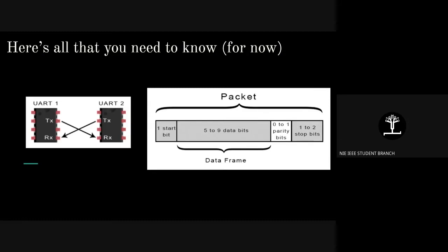First, whatever data is to be sent is initially on a bus, and from the bus, the 8-bit data with the start bit gets latched into something called a data register. We have a data register where all the 8 bits will be filled, and in parallel from the data register, it gets shifted onto the shift register. The shift register's job is to append a stop bit behind, and then serially output one bit after the other. So all 9 bits will be sent, including the stop bit, and then another packet if required, or if not, not required. So that's how UART actually works.